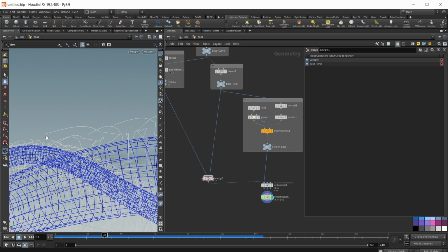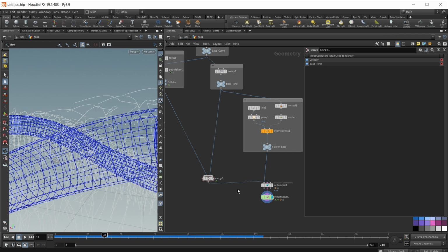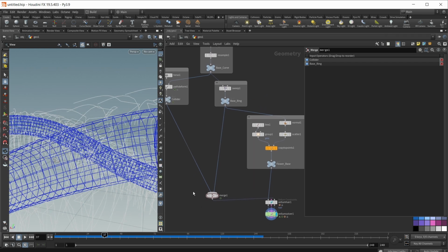What I can see happening if I take a look at one single hair is something that looks a bit odd. We have our standard hair curve right here, and then we have this jump, and then we're back at a normal hair curve. And this is simply because our collider here, our base collider, is a bit too big, and this pushes some of the hair points up to one side, which leads to all those kinks on those hair curves. There's a simple way I can fix this.